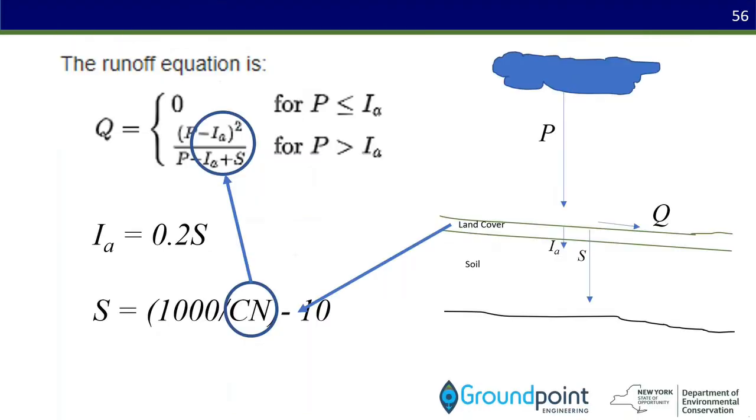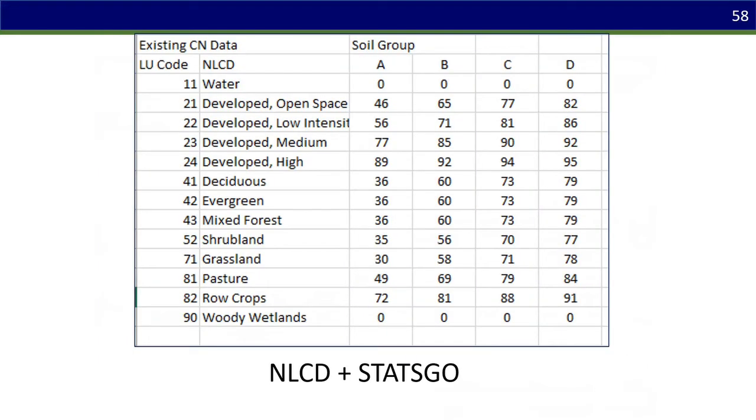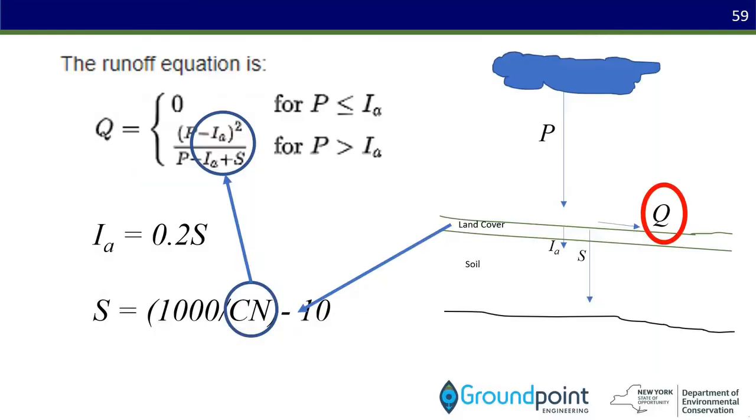So one of the cool things is that it's GIS based. Now, this is not a hydrology class, but in order to solve the hydrology equations, we need something called a curve number, right? So that's essentially a runoff coefficient that handles infiltration. So that comes from land cover and soil type. So there are tables in TR55 in the documentation for estimating this curve number. But the folks at Cornell did a really nice crosswalk with the national land cover data and soils to get a standard curve number layer across the Northeast region from Pennsylvania to Maine. So we have that as a GIS input layer.